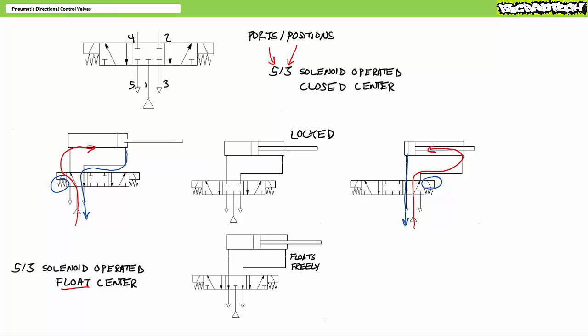In conclusion, this lecture examined pneumatic directional control valves. We learned a directional control valve stops, starts, and changes airflow direction in a pneumatic system, ultimately influencing the direction of a pneumatic actuator. We discussed ports, positions, and actuation methods, and examined simple applications of 2x2, 3x2, 5x2, and 5x3 directional control valves in pneumatic systems. Lastly, we discussed port numbering schemes common in the pneumatics industry.